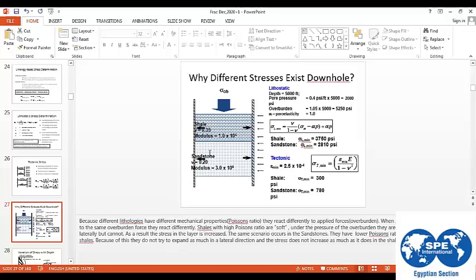But in case he makes this calculation and finds it impossible to design a fluid that does not frac the formation and at the same time controls the well and prevents any influx inside the wellbore, he will redesign the casing setting point to cover this weak zone and drill this zone with less hydrostatic fluid.